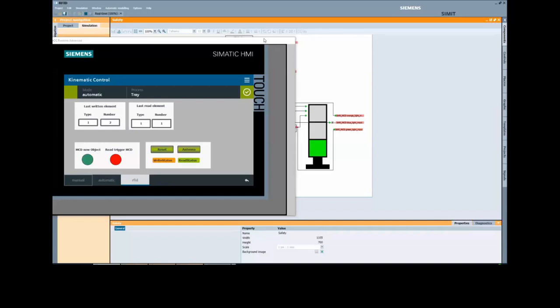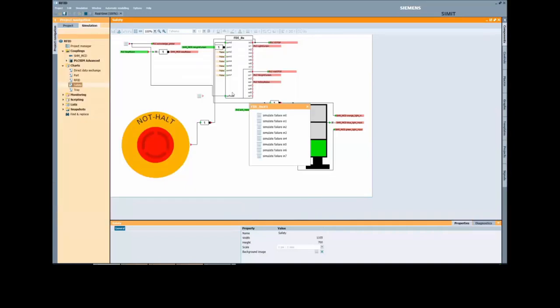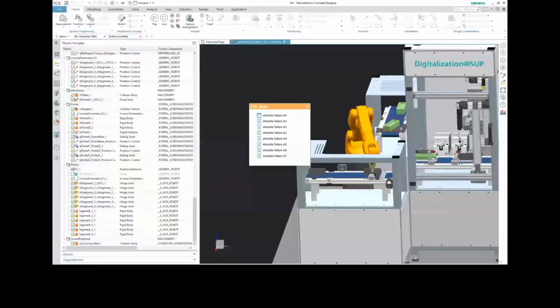What I can also do is try to introduce some channel faults, and I can see how NX reacts to those channel faults or my sequence. So let's say if I introduce a fault in my channel 1, and go back to this, it's probably just stopped there and it's not going to do anything. So we can now start testing, if we are introducing some channel faults, how do we want our sequence to operate, whether it should reset or it should follow some sort of safe procedure, safe sequence, any of that stuff.